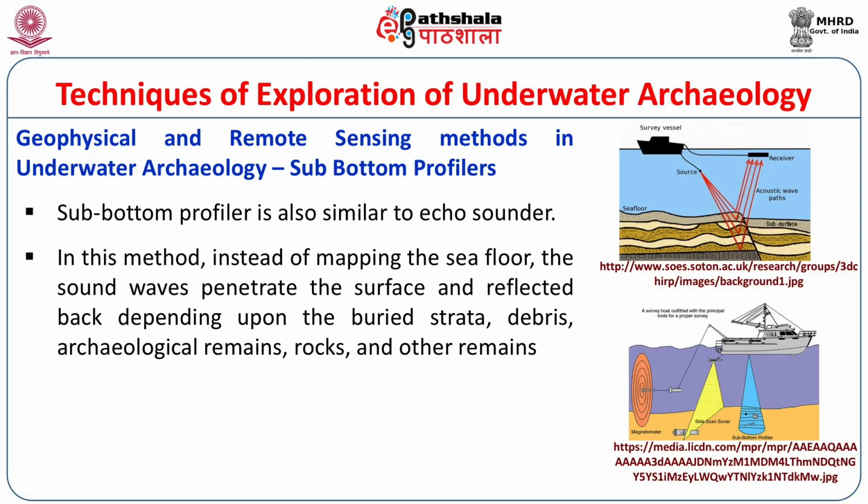But here, the sub-bottom profiler is similar to the echo sounder, but instead of only mapping the sea floor or the lake floor, the sound waves penetrate the surface, like in the case of ground penetrating radar. It slightly penetrates the surface also, and depending upon the buried strata or archaeological remains or rock debris, it can be used to map the buried features also. So this is an advanced system.